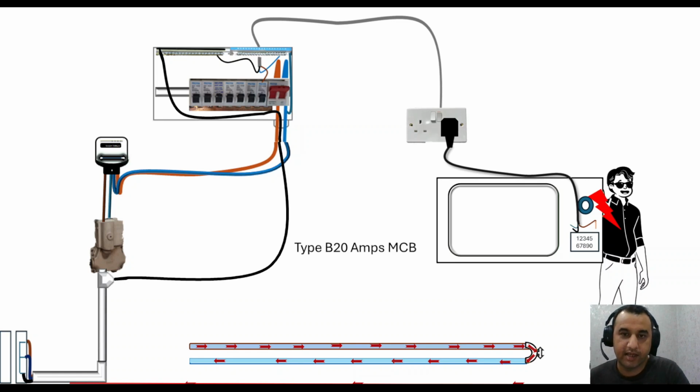This is the final slide. Here we remove this circuit protective conductor, the third layer I mentioned. Now, as I said previously, if it's not connected, if it's loose, if it's disconnected anywhere, in those circumstances the leakage current is going through your body back to the system, the transformer. So this could be very dangerous.